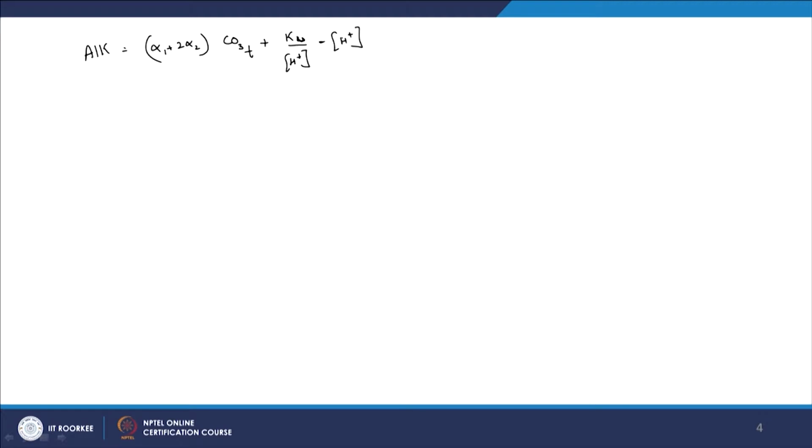So let's say now this is for the mixture, where we mixed up 1 and 2. How do I go about calculating it now? For this case, I can calculate alkalinity. How do I calculate alkalinity now? I can say V1 into alkalinity 1 plus V2 into alkalinity 2 is going to be equal to V3, or the volume of the mixture, into alkalinity of the mixture.